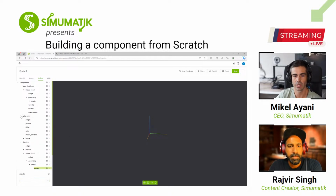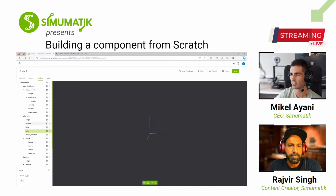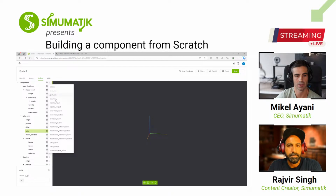And we already know that we want to have a vertical axis, so we can start fixing that. We're gonna select here the axis is gonna be vertical, so we take theta, and we will set up the limits in a moment. We can set the limits, how much it can move up and down, and we will also add some behavior. I was thinking, let's do something simple. Let's click on the element in the different parts and make it move up or down depending on where we click.